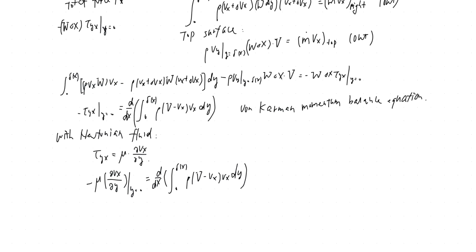Okay, so now if you look at this equation, we have eliminated Vy, or basically this equation only has Vx as a primary variable. You still have delta x, the boundary layer thickness, which we don't know. We will handle that later. So this equation alone is a primary equation in Vx, and we are going to use it to solve for Vx.